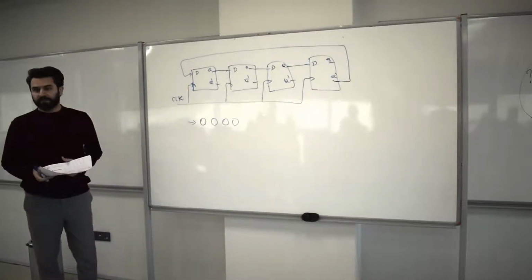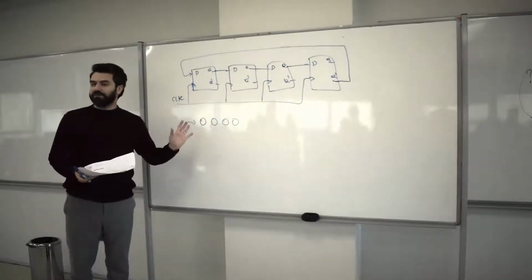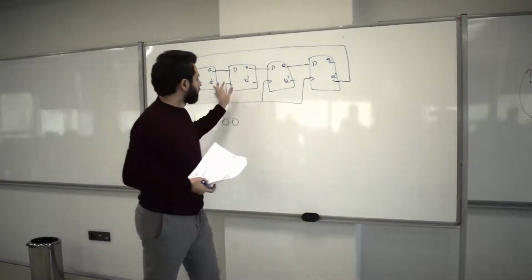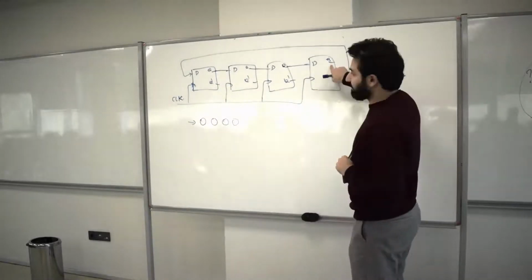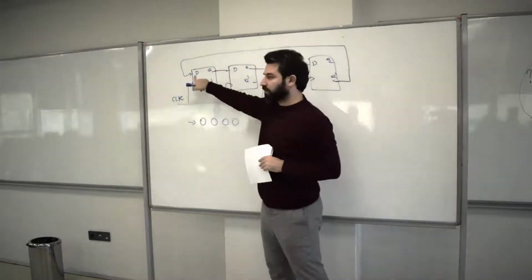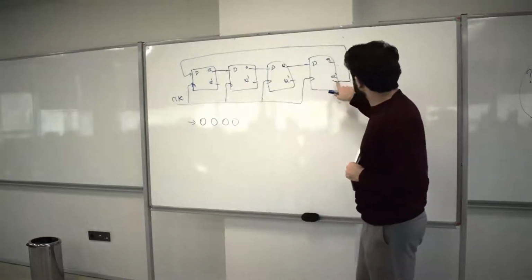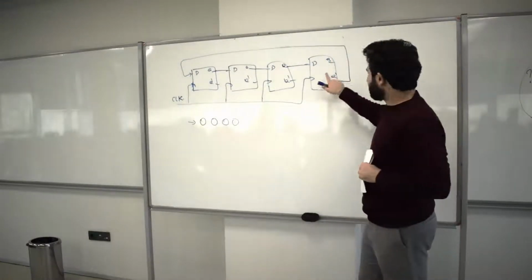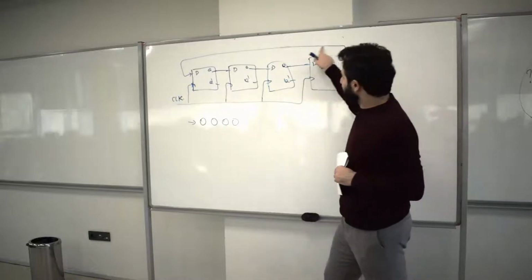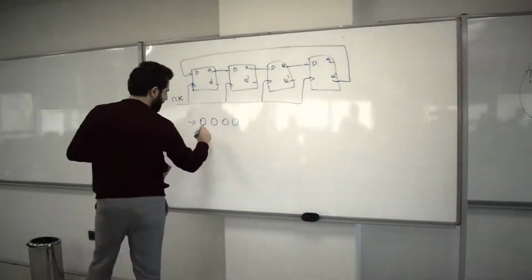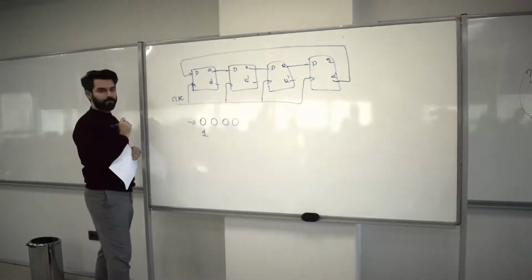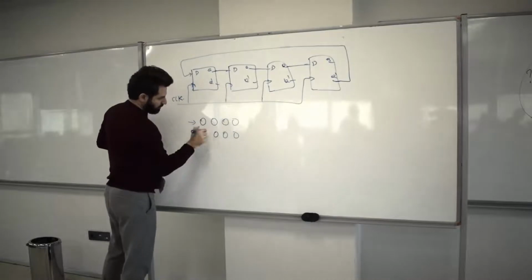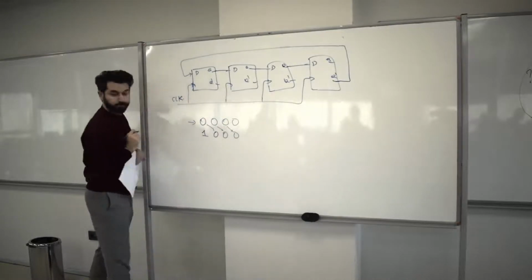Now, would that be all right? Well, we shall see. It will be all right. Why? Because this will generate 0, 0, 0, but you're not really feeding that 0 back to the input of the first flip-flop. You're feeding back Q prime, which is not a 0, it's a 1. So in the next clock cycle this 1 will be shifted onto the first flip-flop, making it 1, and the rest of the zeros will be shifted to the right. All right?